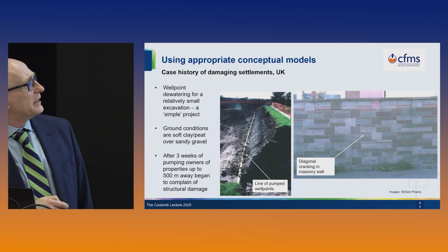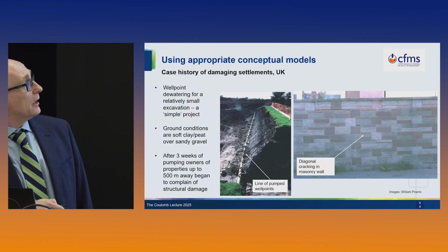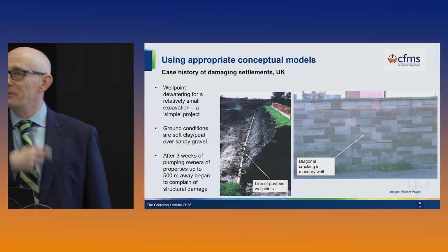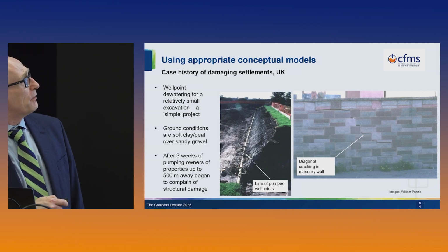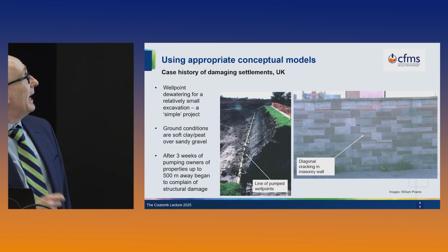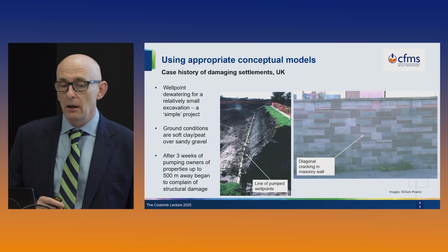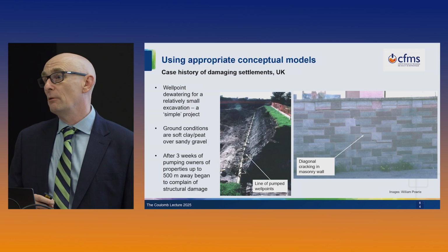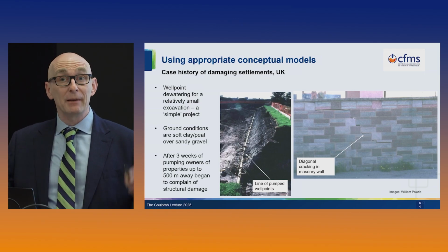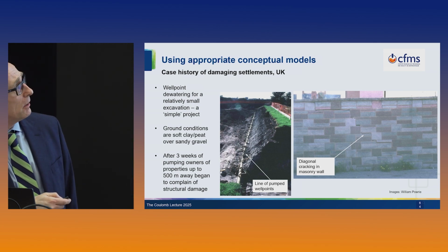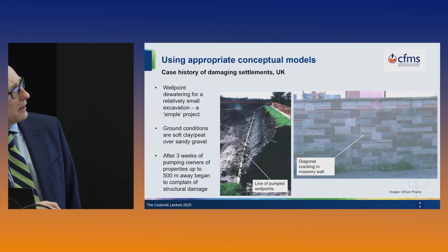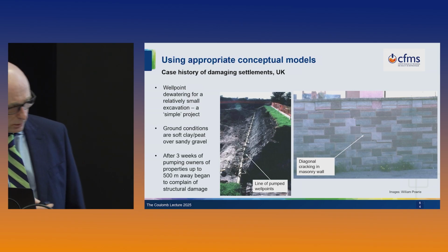Here, this dark soil is the soft clay and peat that's been excavated with a frighteningly steep slope. Again, not one of my projects, I was involved afterwards. There are pumped well points here that are pumping from a gravel aquifer that starts about here. Within 3 weeks of pumping, owners of properties up to 500 metres away reported damage. Not settlement, I mean actual damage. And it's really unusual to get damage at that distance. You can see here, this is a masonry wall, and there's quite a large opening in a crack down through that wall there.